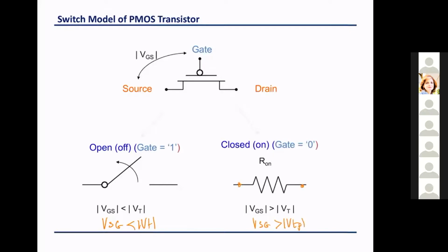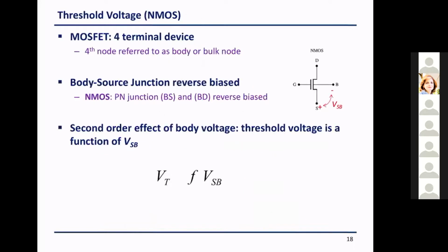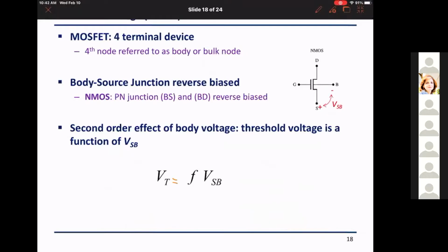Okay, great. Now here, the threshold voltage is really a function of VSB. Meaning the voltage from the body to the source, or the source to the body, matters.